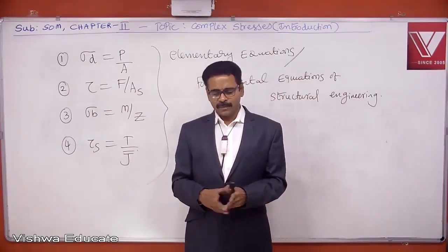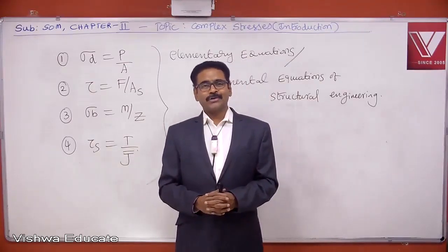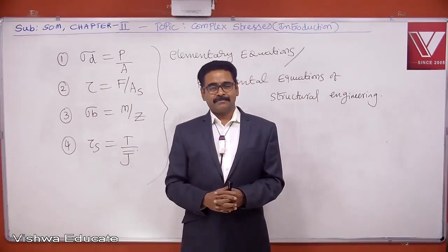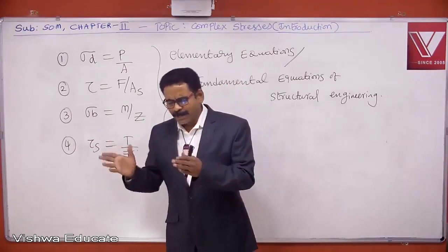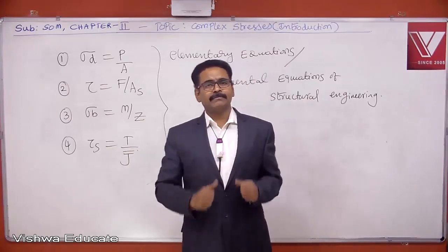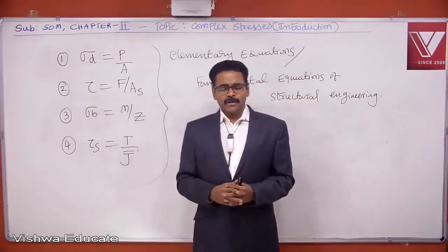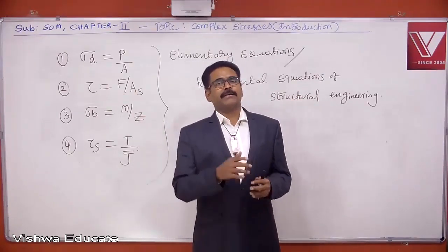That means while designing any ductile structure, you should know how to find the maximum shear. A plane carries this maximum shear, and that plane is called the shear plane. So ductile structures fail because of shear about the shear plane.